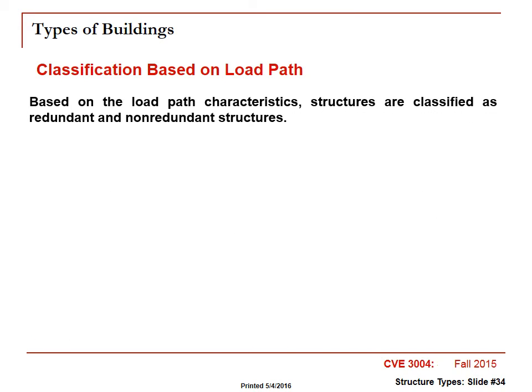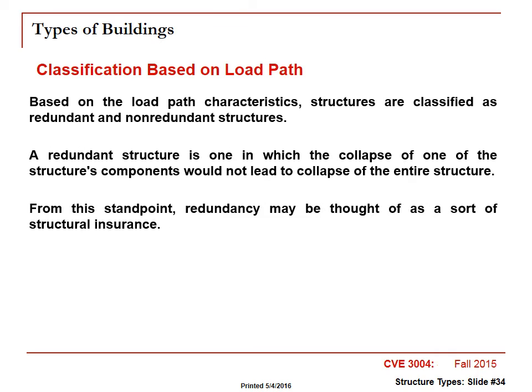Generally, our basic idea is that we like redundancy. I mean, we like bridges where the bridge deck is carried by 6 steel girders. If one of the steel girders fails, you still have 5 left. Although you might have a localized failure, that one bad steel girder won't bring the bridge down.